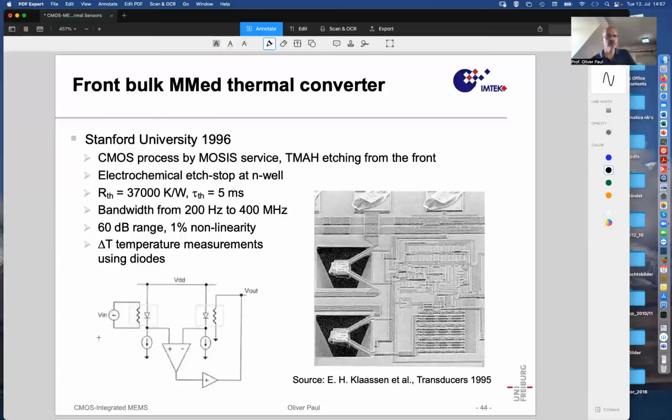So here is this unknown input voltage, this AC input voltage, and then here is this DC voltage that is produced by this differential amplifier. Once the two nodes are at the same potential, this difference is zero, and the system is obviously in the working point that it needs to be in, and that output signal is the equivalent voltage. So this output voltage is equal to the square root of the average V square.